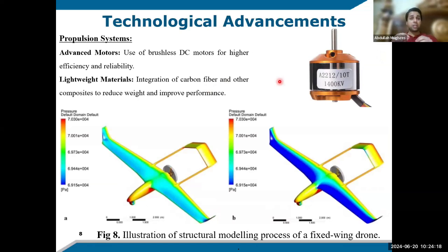Basically, what we do is that if there exists a mission, for example, we have to carry a 500 kg payload, we cannot use multi-rotor systems. We have to go for fixed wings, and we have to increase the size of the wings. We will calculate that this wing will generate this amount of newtons of force, and this amount of force will carry like 450. We need to increase the size further. We design the drone in accordance with the mission.